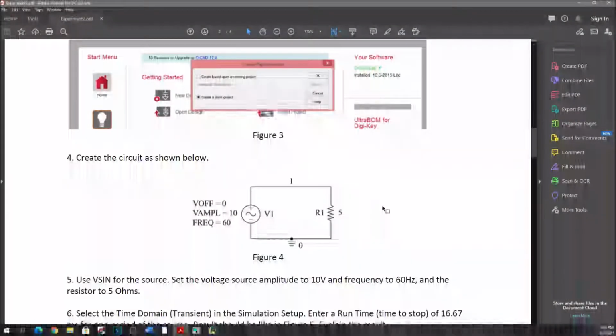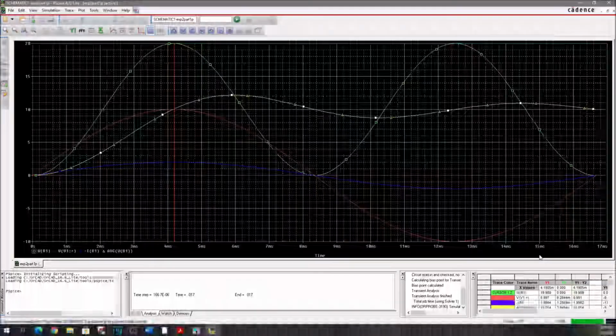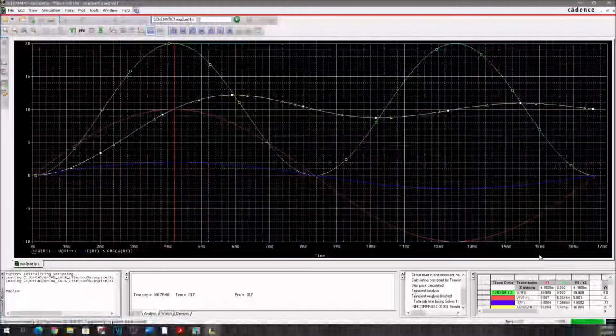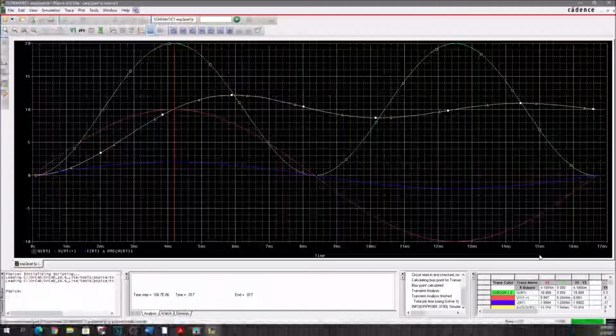The measured input voltage signal in the simulation also has a small difference from the theoretical value of 10 volts. We recorded a value of 9.998 volts. The formula for the instantaneous power is equal to voltage multiplied by the current. So based on the circuit, 10 volts times 2 amperes is 20 watts. And based on the simulation, we recorded an instantaneous power of 19.989 watts, which is near to 20 watts.